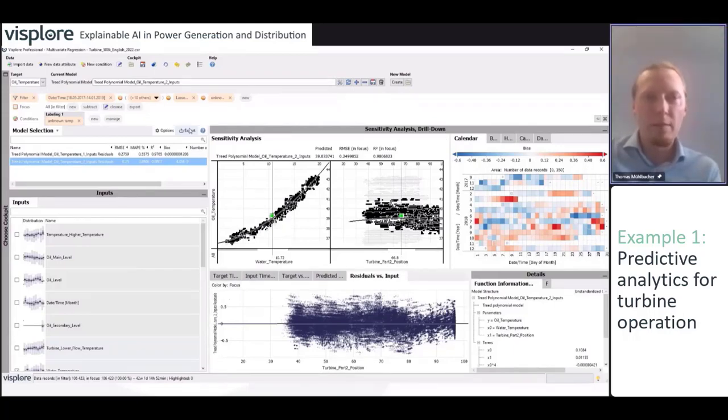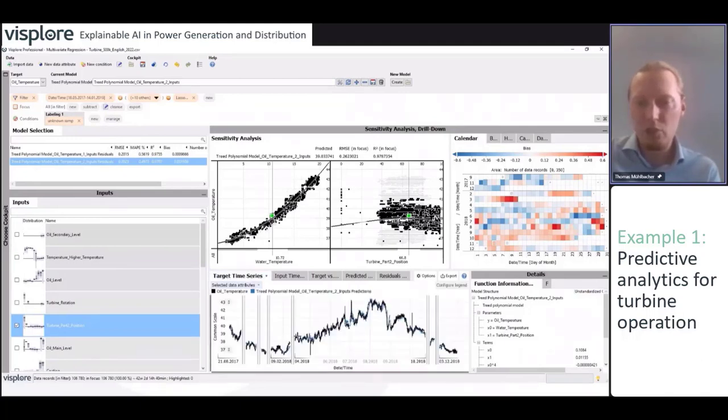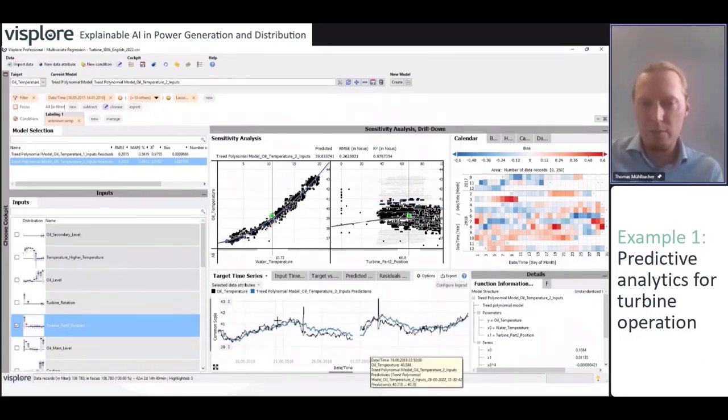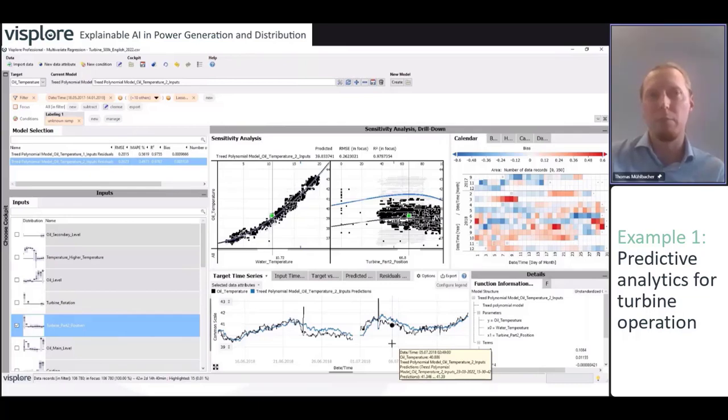Maybe also just one thing, we have these unknown ramps here that we had excluded, so maybe let's include them again in the visualization and look at the actual prediction that we have made here as a time series. And you see here now, our prediction time series is in blue and the measured values are in black. And you would nicely see that these unknown ramps that we have in here are quite strong deviations from our expected modeled behavior. And by defining a threshold here, for example, like 1 degree or a bit more, these would actually be able to be recognized for condition-based monitoring, for example.